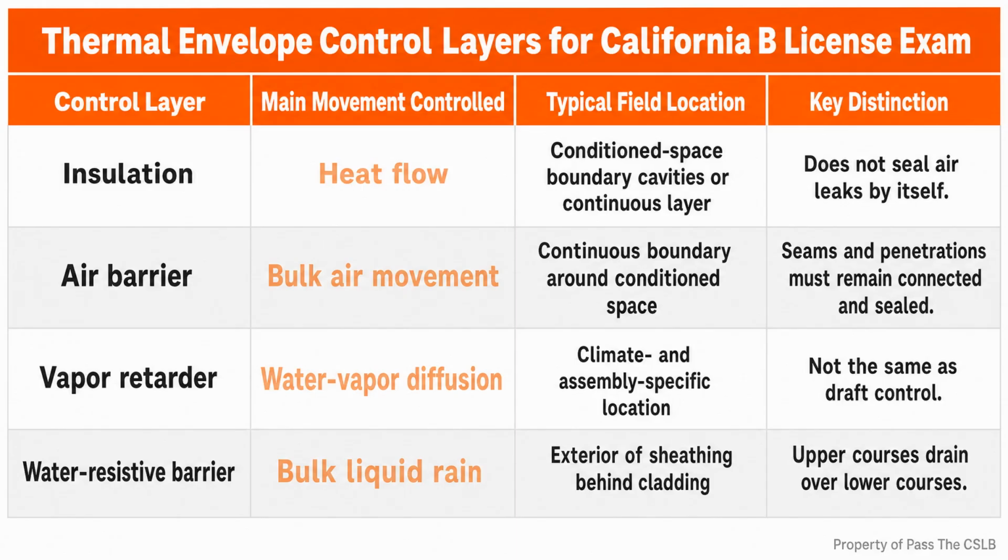The most useful supervision example is an exterior wall behind a fiberglass tub, shower, or fireplace enclosure. Once that large unit is placed, the backside may be inaccessible. The solid air barrier belongs there first, sealed to the framing before the fixture blocks access. If the sequence is reversed, the later choices are bad choices: accept a concealed break, or remove work that was already installed.